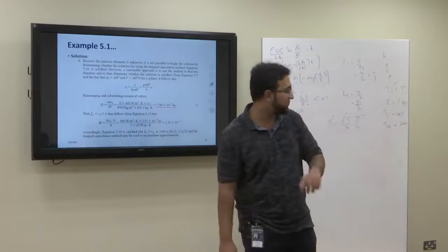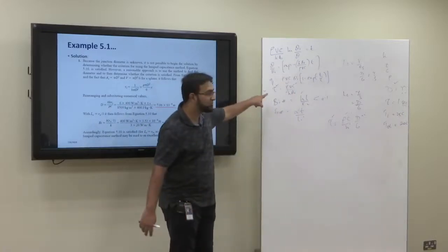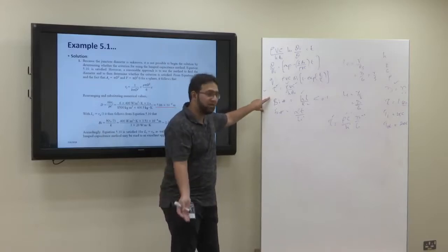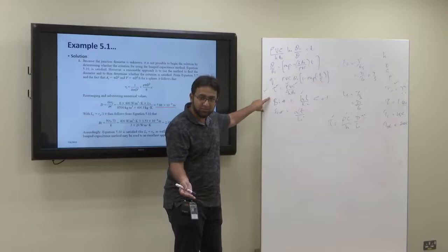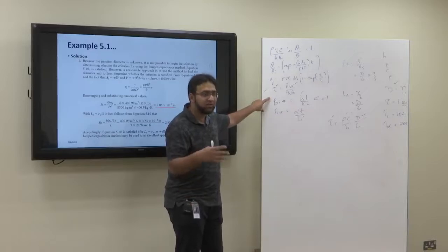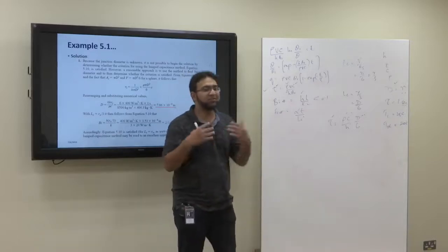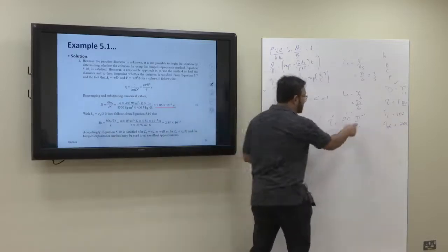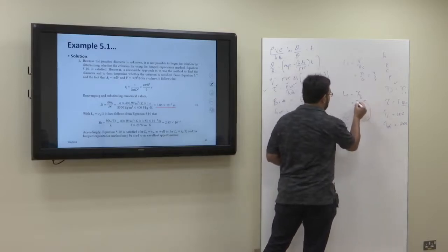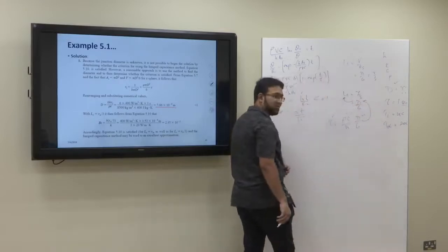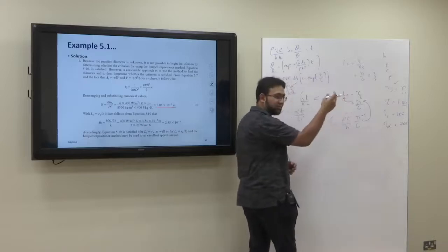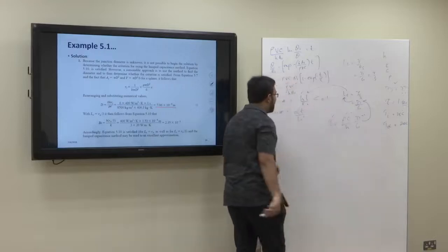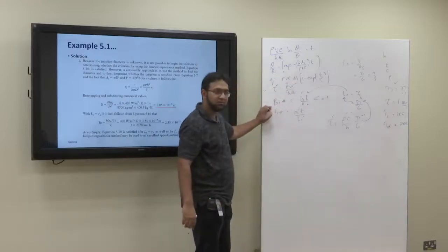Because this diameter was found based upon the formula for the time constant, but this formula came only if the lumped capacitance analysis is applicable. So we need to check whether our calculation is correct or not. Since we know the diameter, we place the diameter here and get the characteristic length. Once we know the characteristic length, we place it in here and find the Biot number.